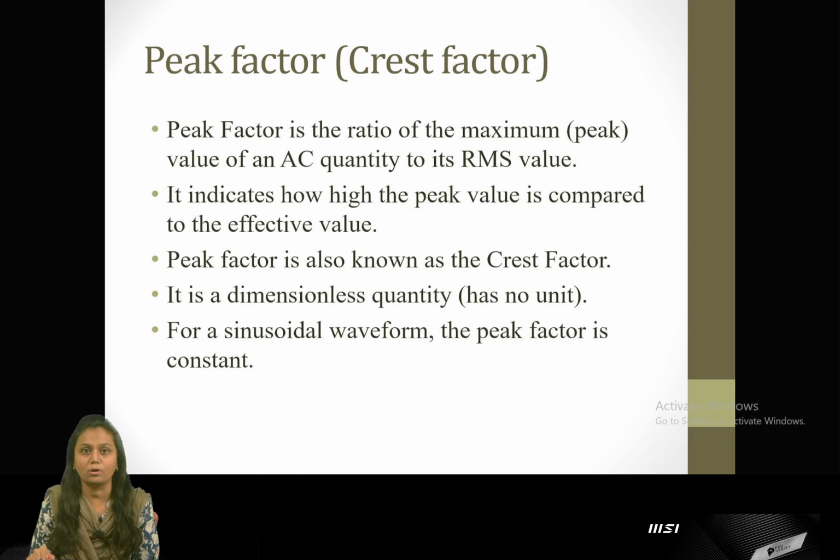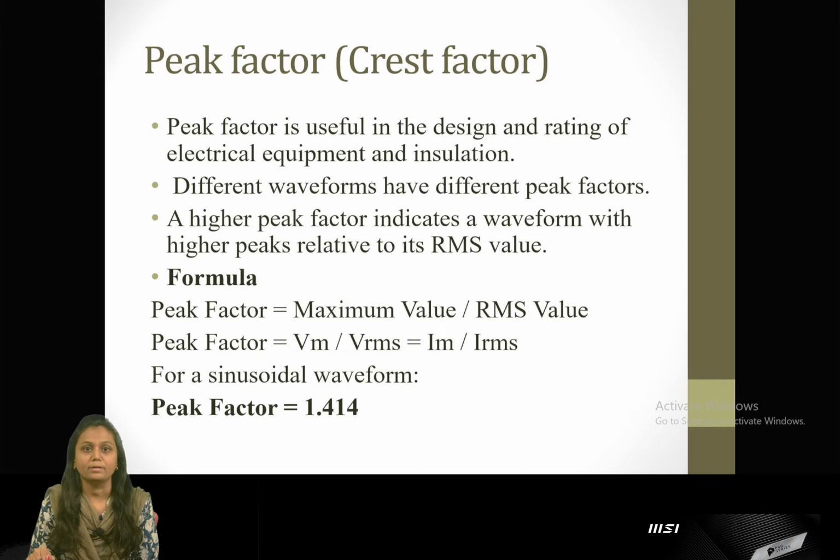Peak factor is the ratio of maximum value of an AC quantity to its RMS value. It indicates how high the peak value is compared to the effective value. Peak factor is also known as the crest factor. It is a dimensionless quantity, meaning it has no unit. For a sinusoidal waveform, the peak factor is constant. Peak factor is useful in the design and rating of electrical equipment and insulation.